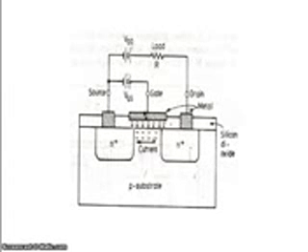Now let's go into the details of the principle of operation of a simple planar MOSFET. So in this figure, assume that the gate is open, that is, no supply is given across the gate and source terminals. Then the junction between the N+ region below the drain and the P substrate is reverse biased by the input voltage VDD. Hence, no current flows from the drain to source and the load, since this junction is reverse biased.